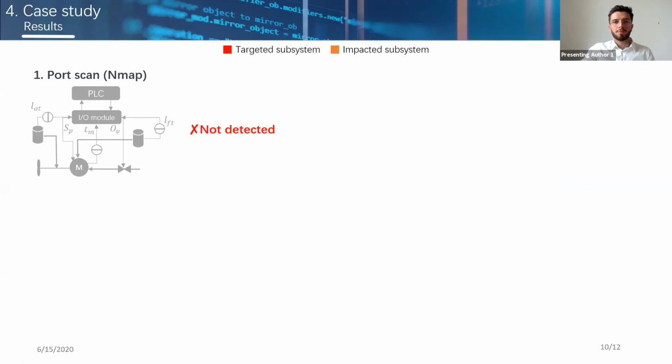And once the system's graph model and associated quality evaluation metrics were defined, experimental tests were carried out to verify our approach. The quality evaluation process begins when the sensor receives data as an incomprehensible binary sequence. Next, information is defined when the data are decoded by the corresponding protocol, and context gives a meaning to values. So there are 5 scenarios that have been examined: normal functioning conditions, a port scan to detect all open ports, a PLC stop to turn off the PLC, and 2 man-in-the-middle attacks, one on the propeller rotation speed control commands, and another on the valve opening control command.